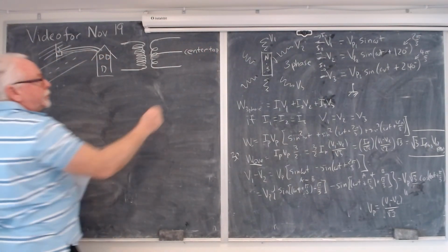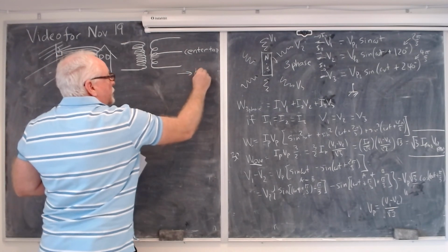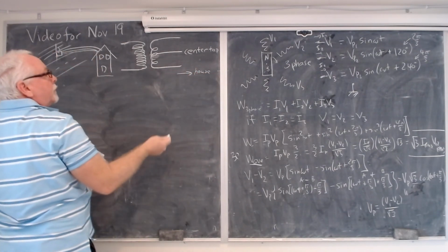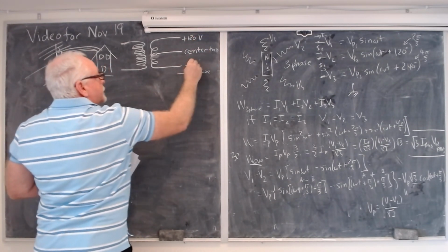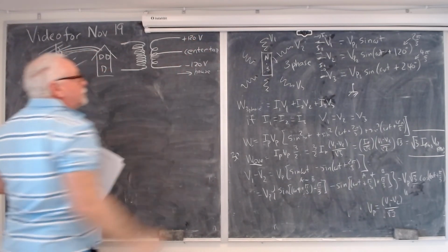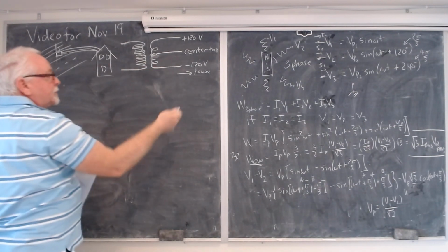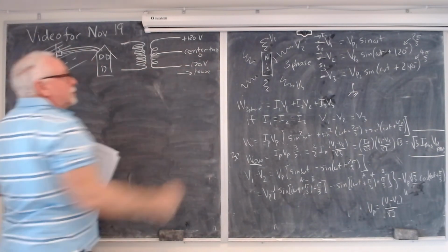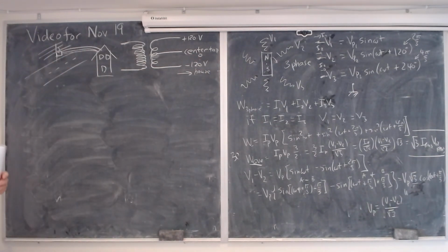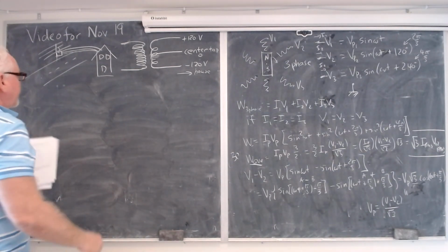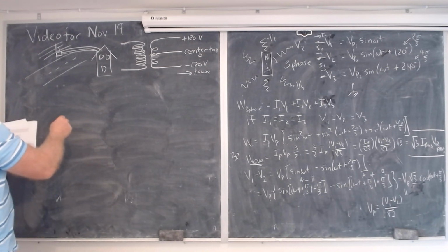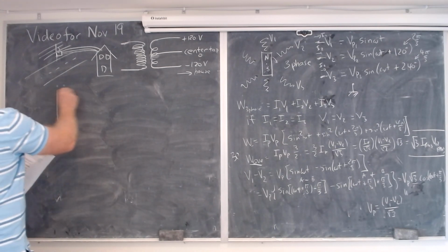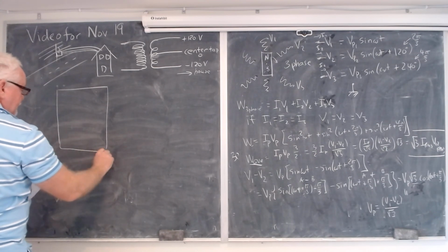And so going to your house, you have plus 120 volts and minus 120 volts, and then a center tap, which is basically 0. That'll be connected to ground in your house. And so in your house, if you go to your breaker box, which is this box that has a bunch of switches in it,